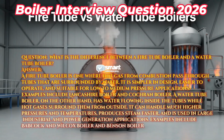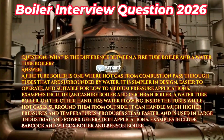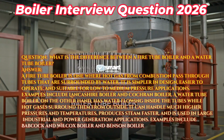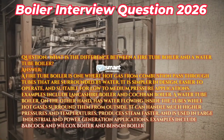Question: what is the difference between a fire tube boiler and a water tube boiler? Answer: a fire tube boiler is one where hot gas from combustion passes through tubes that are surrounded by water. It is simpler in design, easier to operate, and suitable for low to medium pressure applications. Examples include Lancashire boiler and Cochran boiler.